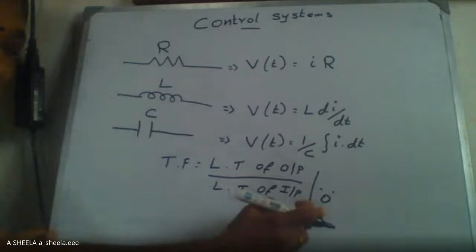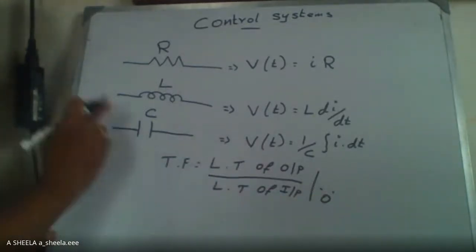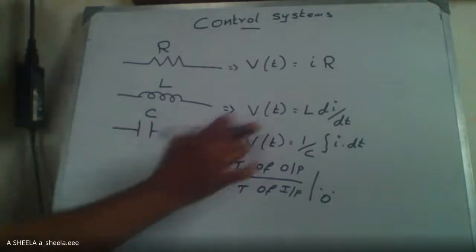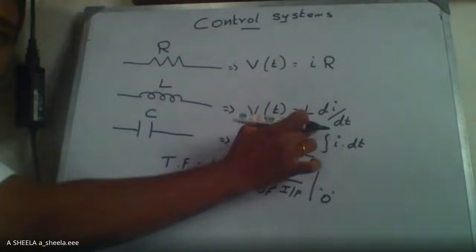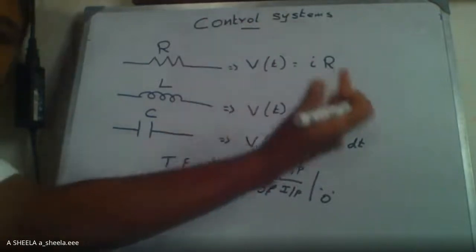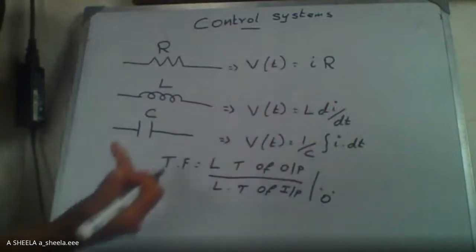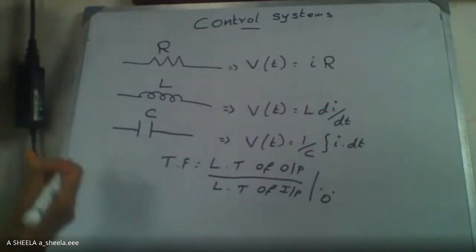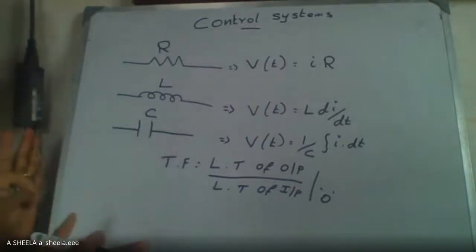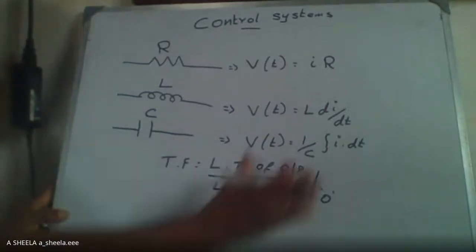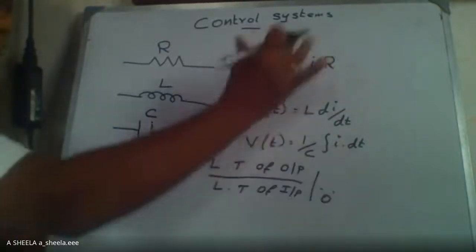Since this is the condition considered for the transfer function, when we are taking the Laplace transform, even if we have a differential of one term, we are not going to extend the Laplace transform with x of 0. We'll stop only with the input variable x of s. That is the main thing we have to remember. Okay, considering this in mind, I'll write the Laplace transform of the individual terms alongside.